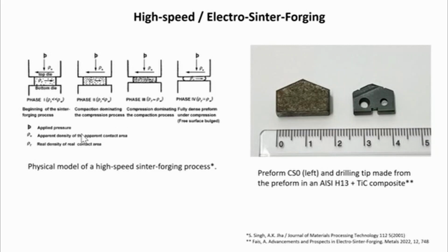Electrosinter forging is an industrial single electromagnetic pulse sintering technique to rapidly produce a wide range of small components of metal, alloys, intermetallics, ceramic and nanocomposites, including ceramic. Electrosinter forging can be described as the superposition of a single mechanical pulse with a single electromagnetic pulse that generates a direct electric current through the powders previously loaded inside an insulating die. As long as we have the superposition of the two pulses, no matter how long these pulses are, we are in the domain of electrosinter forging. If not, we cannot really talk about electrosinter forging, but more about resistance sintering.